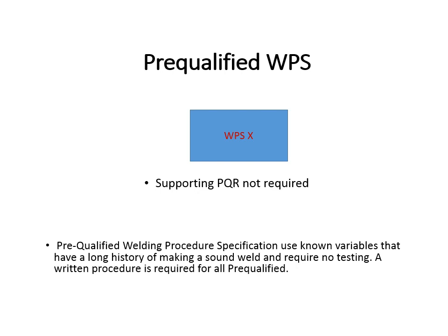We've done this for 60 years. We know that if you weld material A with filler material B, that this is going to be the outcome, and it's probably going to be successful. So that's why AWS allows the use of pre-qualified WPSs if you use Clause 3 to qualify the WPSs.